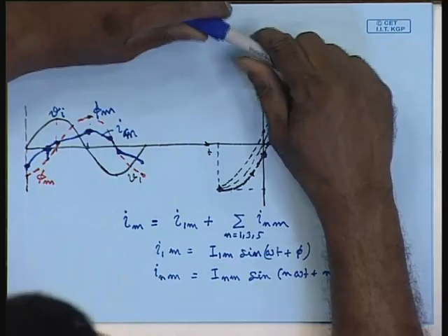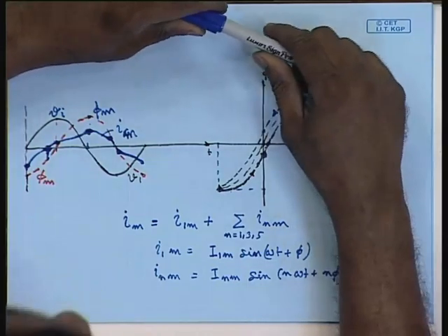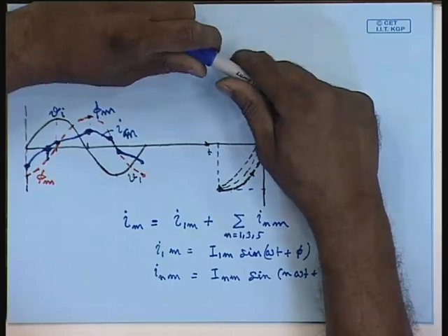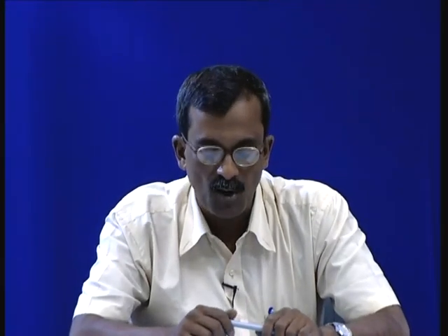Out of phase, that is the component of I m which is in phase with phi m and in quadrature with Vi, that is at 90 degree lagging Vi, is responsible for setting up the flux in the core, while the in phase component of I m, that is the component which is in phase with the applied voltage Vi, supplies the hysteresis loss. Of course, this magnetization current waveform will also be modified by the eddy current component.